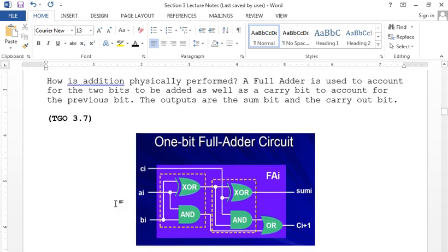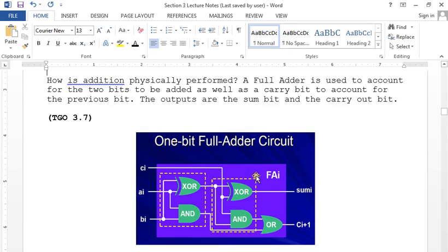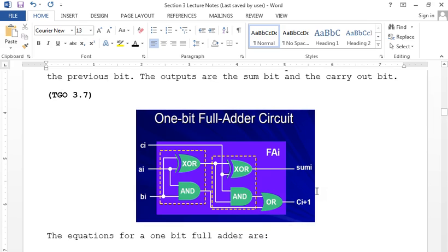Okay. So addition, 1-bit adder, right? Basically we're taking our XOR gates. Are you all familiar with 1-bit addition? 1-bit full adder? It becomes A and B, and so we have XOR here coming into the AND gate for C. So now A XOR B and C, or A and B is our carry bit, and our sum is A XOR B XOR C. So if I were designing this in VHDL, what would I want to worry about?